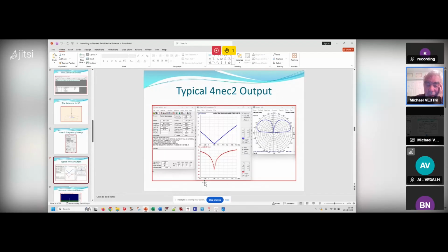The whole length of the bottom was 3 feet off the ground, and eventually you come to something you're reasonably happy with. And it doesn't really matter as long as the measured impedance, which you can measure as well, is more or less right. It's got to be, because there's no tuner on the radial on the QCX. It's really important because otherwise you can fry it.